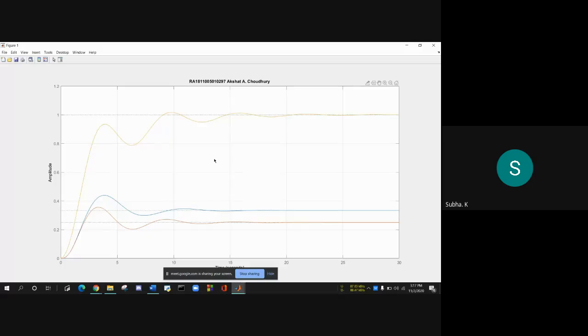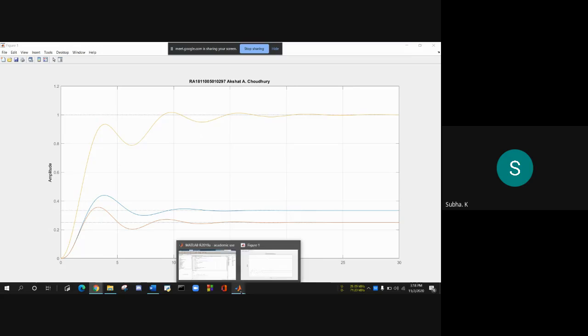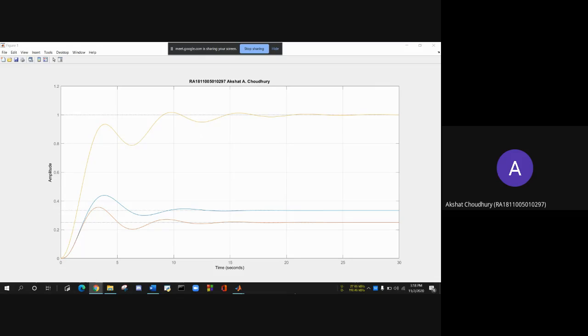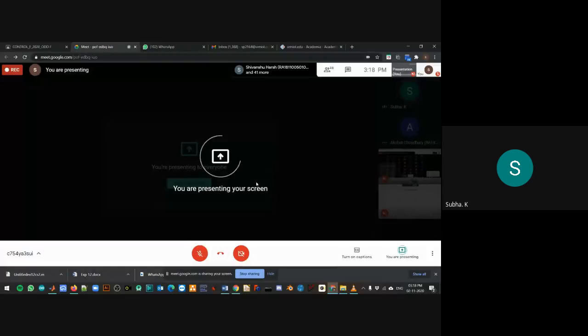Now your overshoot is completely below 1. Your rise time will reduce now. So you have to pick the correct parameter to vary. Random variation will be like this. Initial rising up to 1 is not there, no? Yes, ma'am, that is the problem. So you have to pick the TD and you have to reduce. Okay, what about the other two codes? Finished? Yes, ma'am.